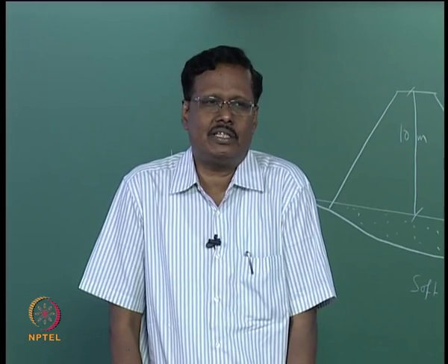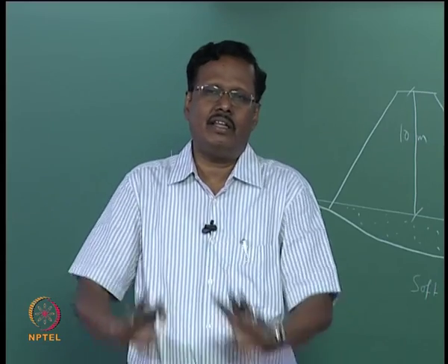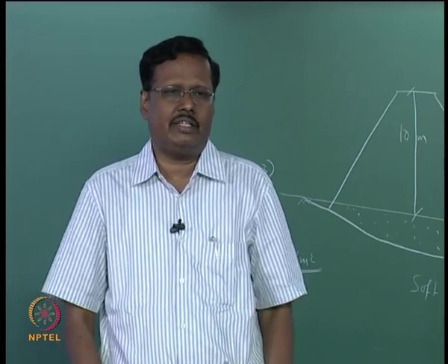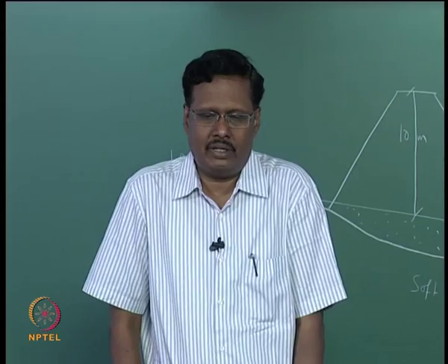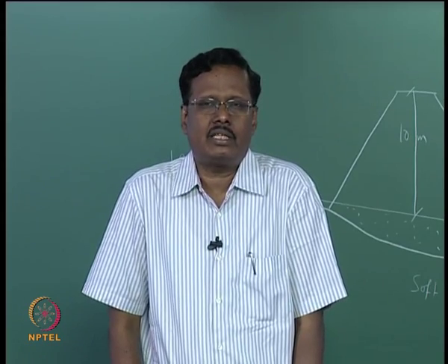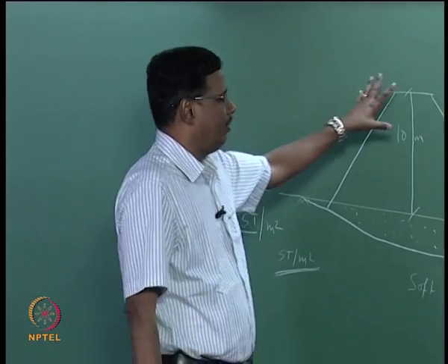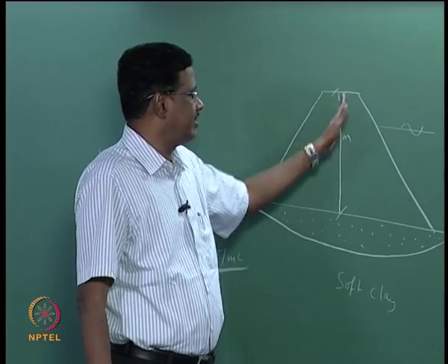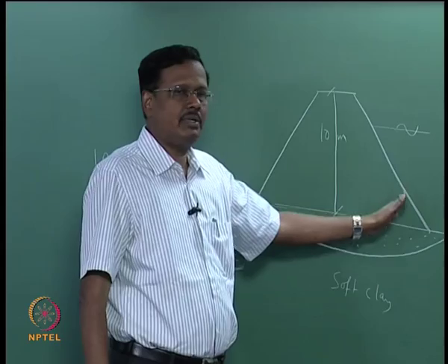So if you put this on top of this soft clay deposit, all this soft clay will go to the sides or go to the forward end, it will not remain there. It will be called a mud flow. That is what is given in the last point, lateral flow under surface loading. When you put the loading, the lateral flow will take place. So here the intensity of pressure will be high, here the intensity will be less.